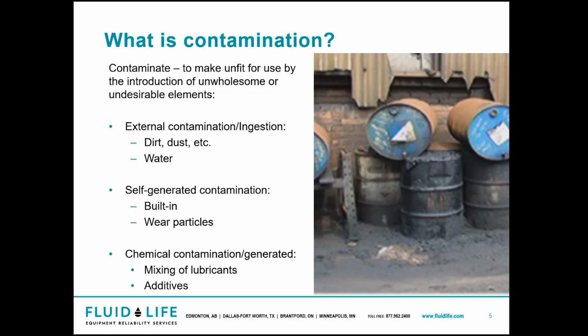Chemical contamination, that could be mixing of lubricants. And what I mean by mixing of lubricants is like mixing gear oil and engine oil. Big no-nos. You don't want to be mixing these different oils because they have very different additive packages that do very different things. And don't be adding third-party additives to oil unless the lubricant manufacturer specifically says you can add this additive to help with this property. In most cases, the additives are far more detrimental than they are beneficial.